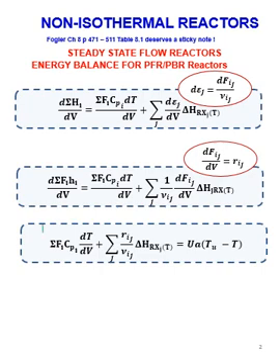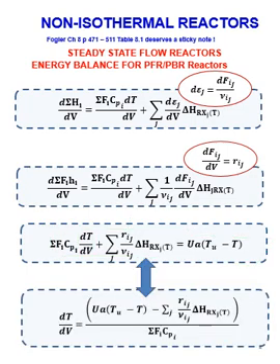This is the shape of my energy balance, and I am going to manipulate it so that I have the differential equation dT/dV as the subject of that equation, because we want to integrate numerically over that volume range of my reactor and see how the temperature is changing. Of course, the rate of the reaction will be a function of temperature and composition at each point as I integrate through my reactor. So once I make dT/dV the subject, this is the shape of my energy balance over a plug flow reactor where I have multiple reactions taking place.